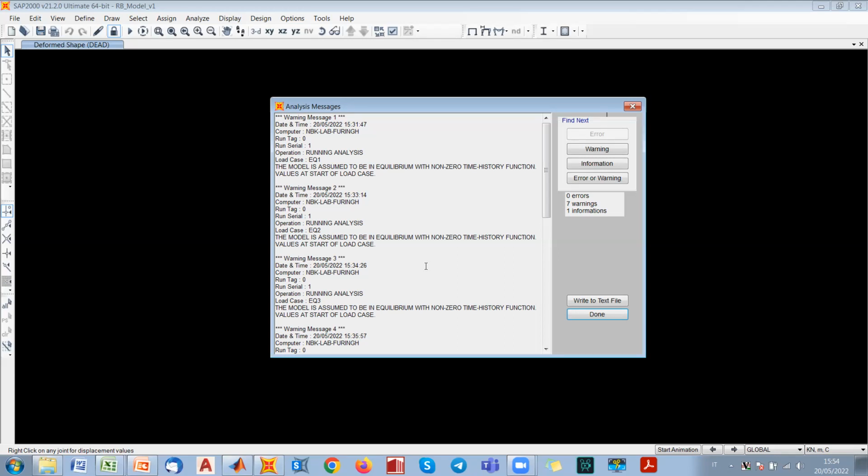Well, that is a very good question, because we can get some sort of additional hardening when we go through very high values of the lateral shear strain for lead rubber bearings. For a very fast evaluation of the displacement demand, this could actually be neglected at the beginning, but it is a very good contribution for the isolation devices if it is considered and modeled for very severe earthquakes.